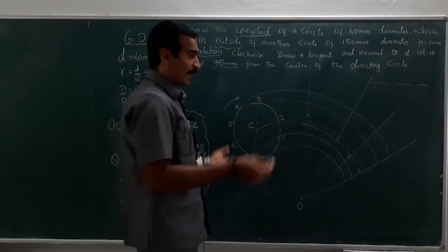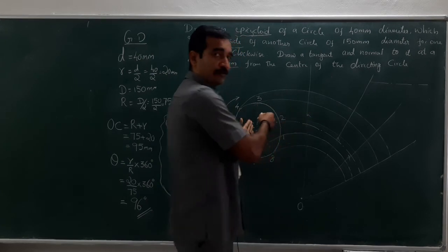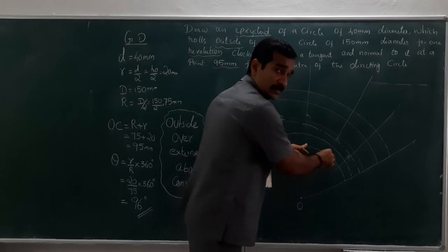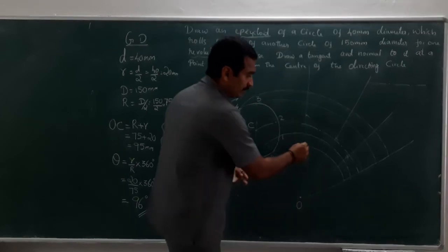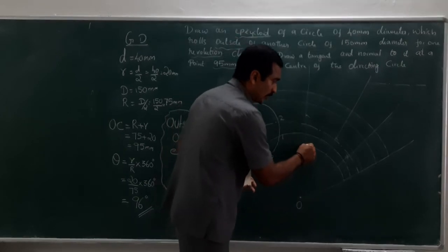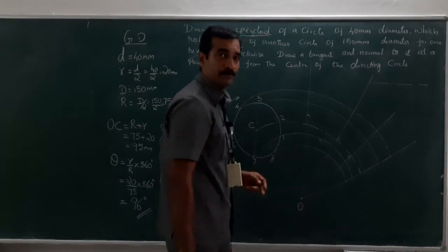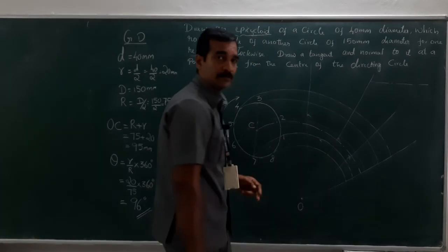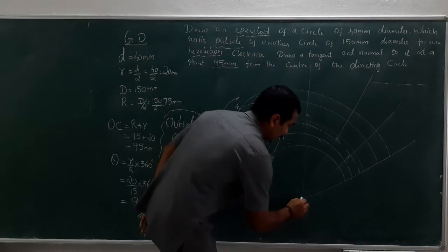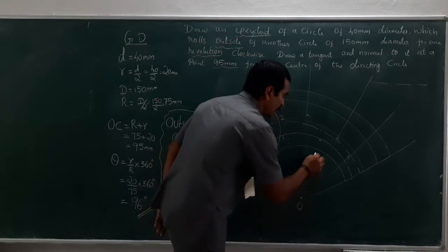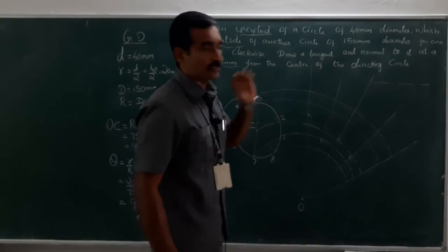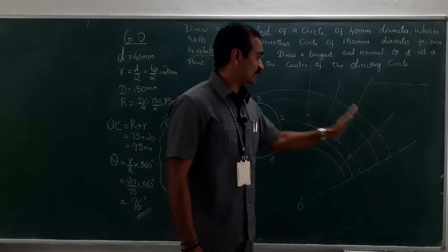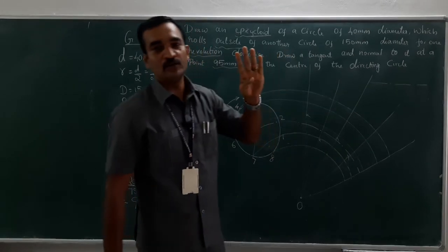In the same manner, I am going to repeat to bifurcate or split or divide. Now, these are my 2 extreme points. Keeping the compass here, taking more than half of this, cut an arc here. Change the position, keeping the compass here, cut an arc here. Now, this is the intersection. Now, draw a line from O passing through the intersection. Look at here. The one half of this particular segment has been divided into 4 equal divisions.